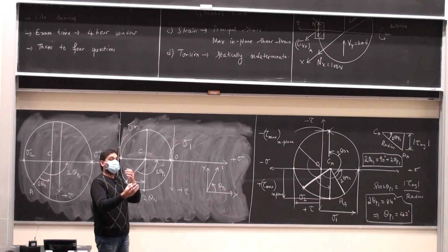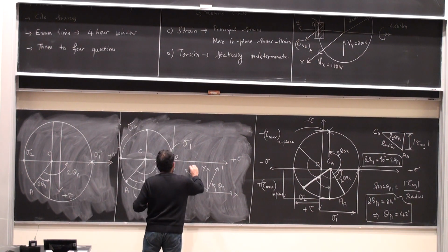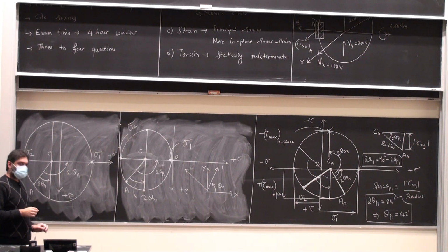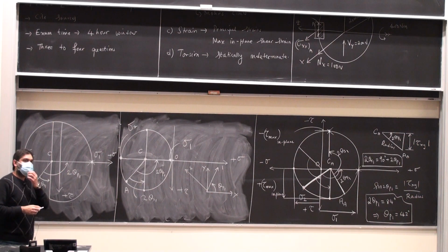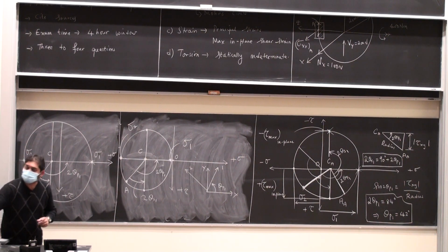I'm good to go because my 2 direction is going to be perpendicular to it. So whenever we're drawing the principal state of stress, 2 theta P1 is sufficient to draw the entire orientation, because you're just shifting from the x-axis by whatever that is. Absolutely. And then theta P2 or sigma 2 would just be the perpendicular one. Absolutely. Okay. And so there are 2 other hands, but I want to point out one more thing.